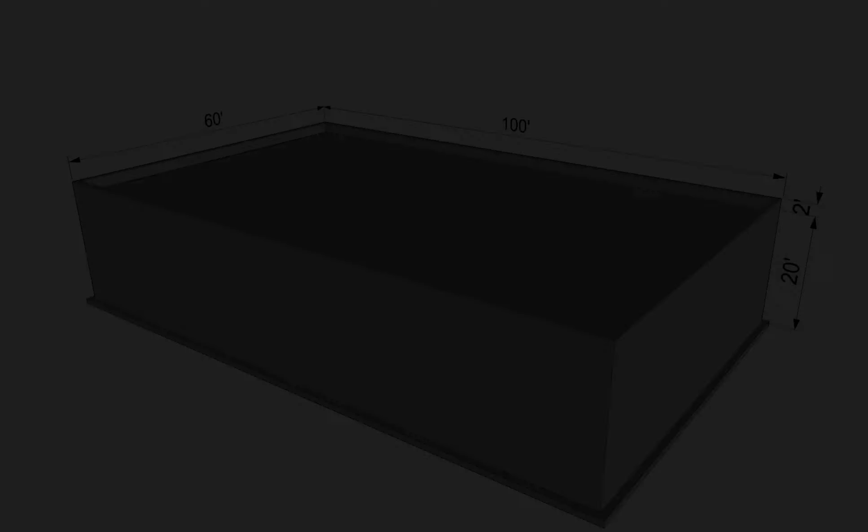And most importantly, understand what elements are supporting what other elements and how this idea of continuity of transferring the force from element to element occurs. So we're going to start with looking at a box-like building and just calculating the magnitude of the gravity loads, or the dead loads I should say, that in turn are activated by the seismic force and how that translates into a static load that we can then analyze as it propagates through the building.